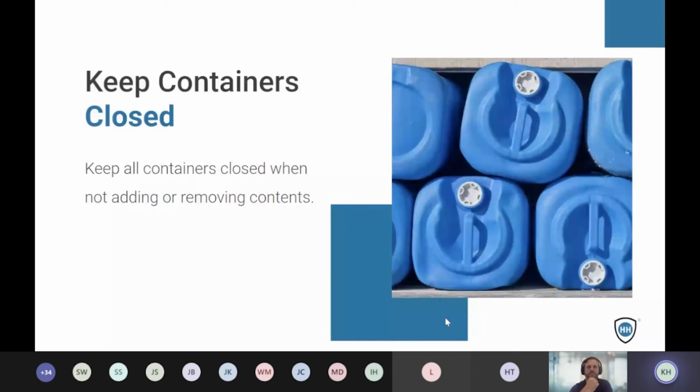So whether it's a hazardous material or even something that isn't necessarily hazardous but could be a problem when it gets into the water, it's a good general practice to keep every container closed when you're not using the liquids from it. It'll help you preserve your chemicals, help minimize the amount of waste that's generated, and help keep everyone from misusing those containers as well.